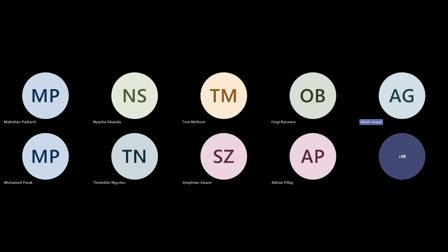However, the main structural element that was actually in that line of distress would be the transverse diaphragm beam, and that incurred shear cracks more towards the inland side, where you've noticed, as per my images, the edge beam had the edge support sheared off.